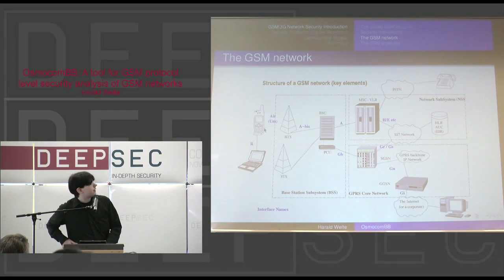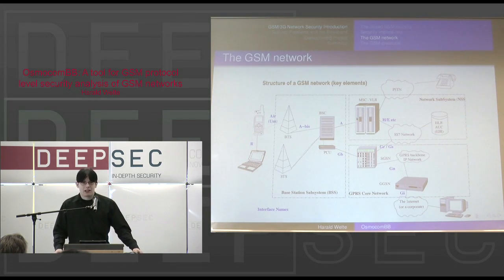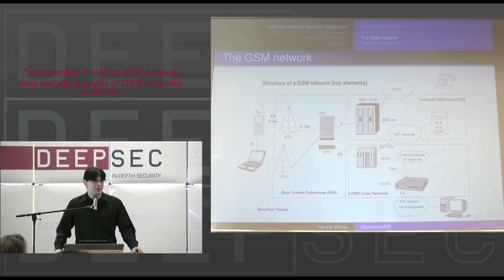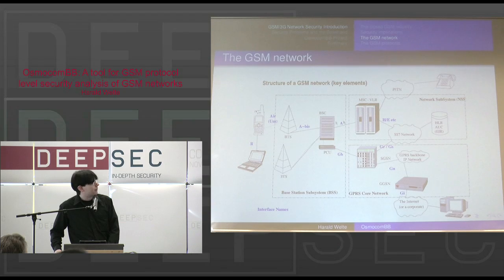And the protocol stack that runs there, there's a layer 1 that runs, of course, only until the BTS, until the antenna. There is a layer 2 that's also terminated here. But then there's a layer 3 that goes to the base station controller or to the mobile switching center, depending on what you do. So if you can manage to implement the layer 1 and layer 2, you can send transparent messages to the base station controller, which controls dozens to hundreds of cells, or actually into the mobile switching center, which operates a large city or half a country, depending on the size of the country. So typically in Germany, for example, each operator has at least one MSC for every major city. This means you can transparently send messages to that equipment.